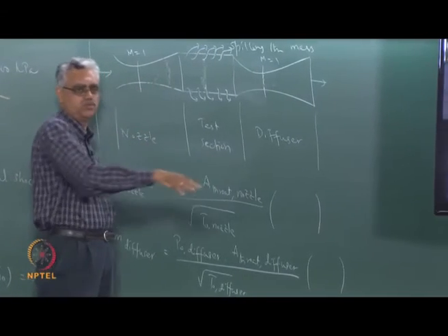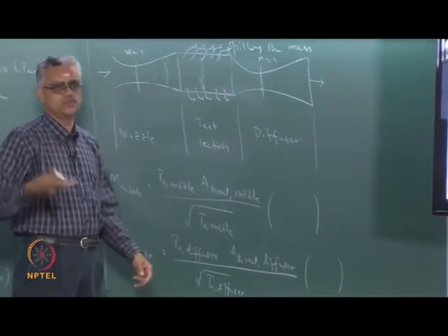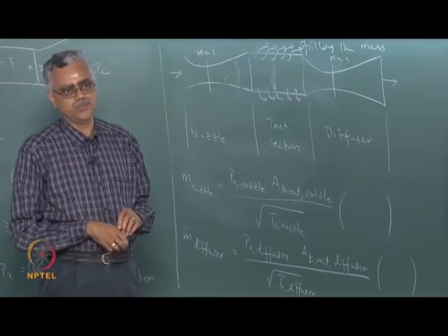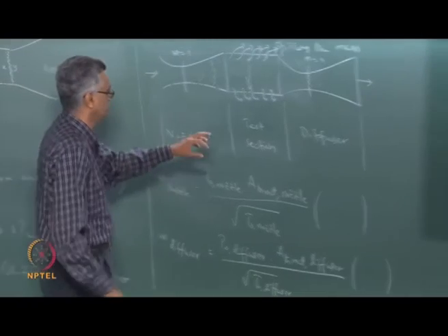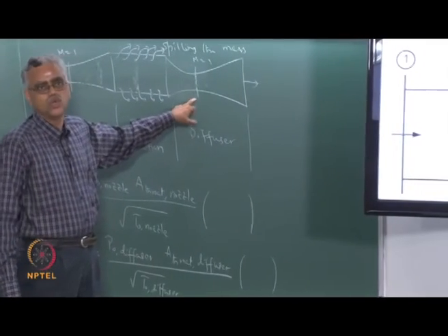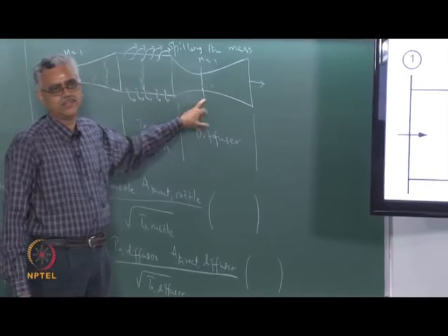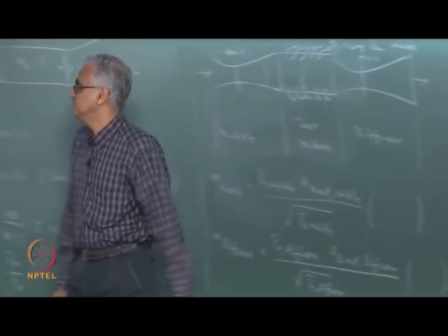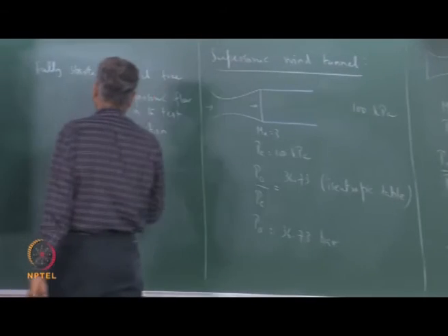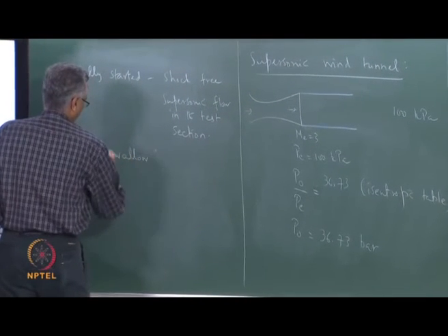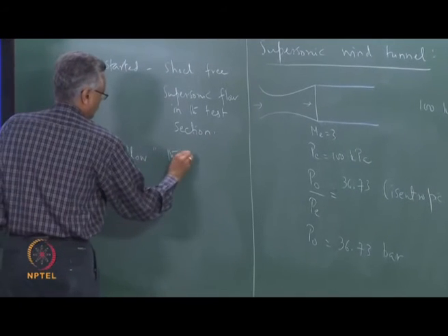It will try to push the flow through this, and again it builds up. So this will go in cycles. So you cannot push the shock through the system simply. The diffuser or the second throat has to swallow the shock. Okay? So that's why if you look at this terminology, swallowing the shock, because you are talking about mass flow rate, the second throat should swallow the starting shock.